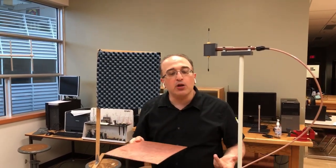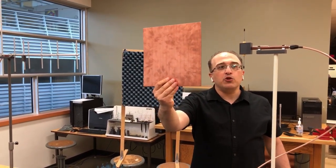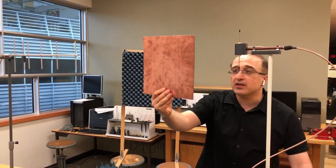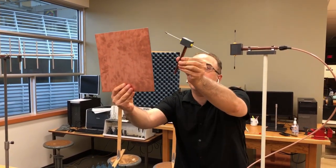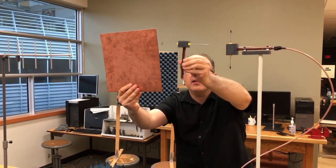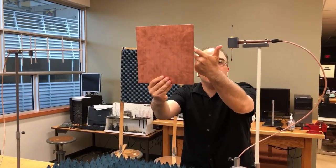Now, assume that I want to do E-plane measurements. This is my E-plane, as I mentioned. How would you perform such a measurement? This is going to be a problem, because if you want to do E-plane measurements with this antenna, the movement should be in this plane, so the antenna should move like that. But this system doesn't do that for you, because it can only rotate in the azimuth direction.